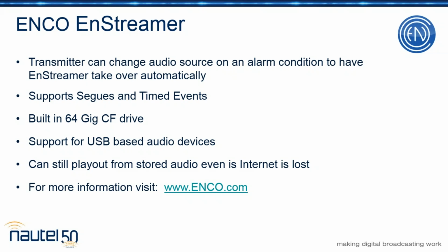If you lose your STL, you can have the transmitter on an alarm condition take a preset, which for the audio would be the audio coming out of the Enstreamer, and have that take over automatically. And to get around some of the limitations, this can do segs, this can do timed events. So if you need to have a show or a broadcast that starts at a specific time of day, you can set that up and have that ready to go.